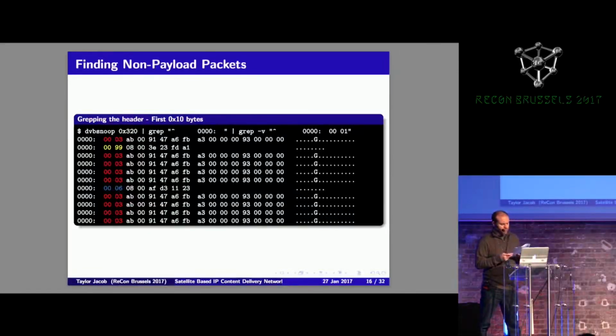The 03 was the most prevalent packet, and it was the longest of all of them. At a quick glance, you could see ASCII strings containing what seemed to be quite obviously file names. I'll come back to this in a minute. The other two packets were the 06 and the FF, and they only occurred before and after a transmission. Their bodies were really short, and it was soon clear that they were used to indicate when a new object ID was starting in the stream or when it was being removed.